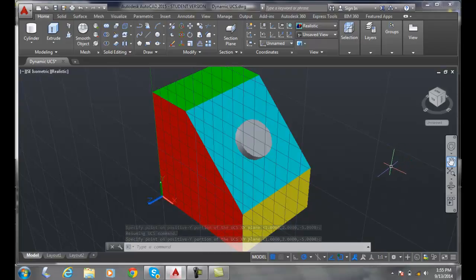In the old days, we did this. We do have some new, better methods such as a dynamic UCS and hovering over the actual icon and picking on the moving a line. I like those better, but the 3-point is a good, solid, kind of an old-fashioned UCS option that works very handy.